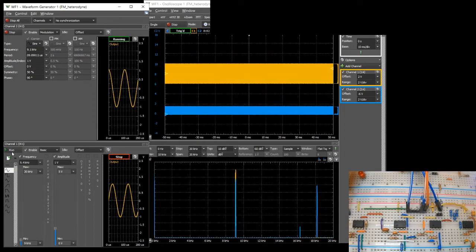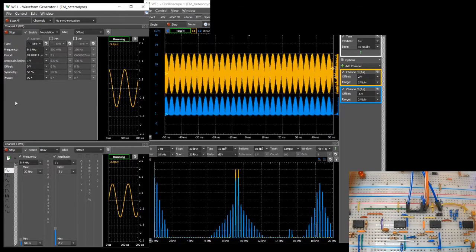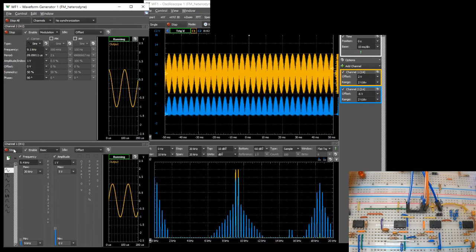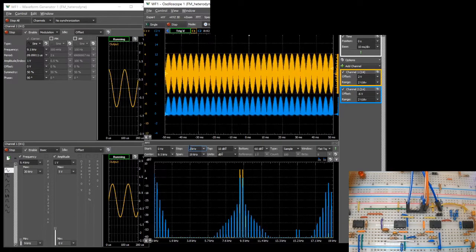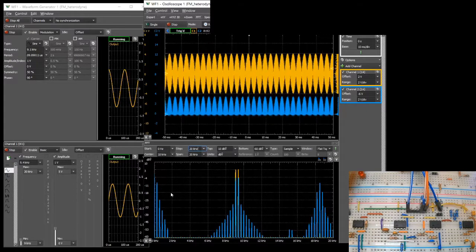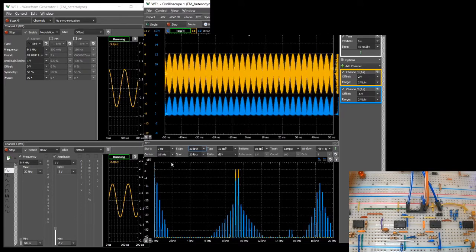Based on the Fourier components that exist only with both signals being on, it is apparent there are three main nonlinear mixing groups. A center group in the frequency range of the original signals is actually of no interest, because they are of third or higher order nonlinearity. A high frequency group involving the doubling and adding of the two main frequencies is also of no interest, because in real applications, they are non-existent because of too high frequency, outside the range of the mixing device, or the power is virtually non-detectable. The only group of practical use and of interest is the low frequency.